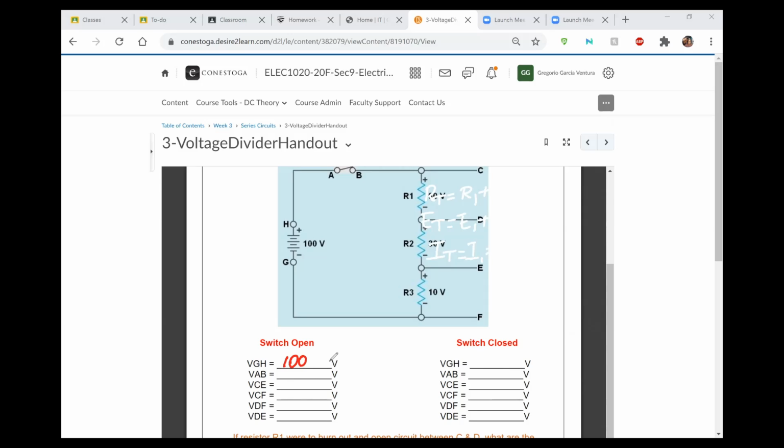I was telling you before everything got interrupted because my computer froze, that I wanted you to be aware of the fact that the highest voltage drop that we experienced so far was on the 60 ohm resistor, because that resistor requires the highest push in order to push the current, which is the electron flow, through that specific component.